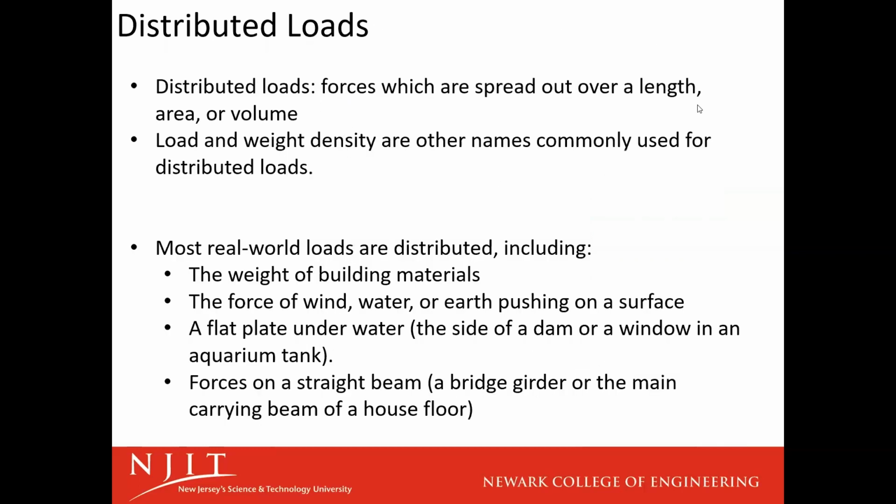Distributed loads are forces that are spread out over a length, area, or volume. Load or weight density are other names commonly used for distributed loads, or any combination of those words: distributed weight, load density, etc. Most real-world loads are distributed, meaning the weight of materials, any material with a large surface area or volume, and beams. That's the last thing, and what we're going to be focusing on are straight beams. But those are all distributed loads.